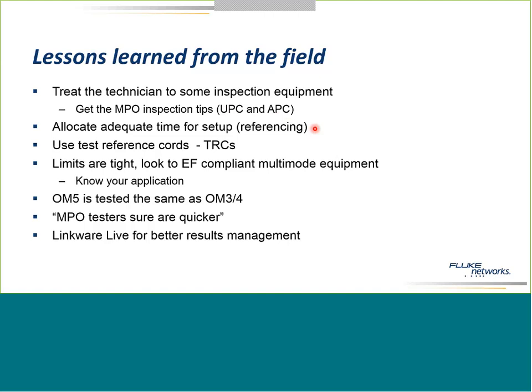If we don't set the reference properly, if we don't follow those 15 steps that we walked through, you're going to get to a situation where you're going to have a gainer. And customers should not accept gainers in a loss test. Something has been done wrong in the process there. So make sure you've got a good reference set up.